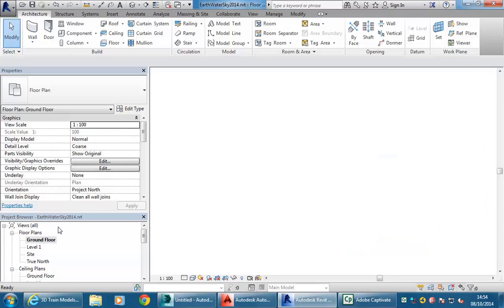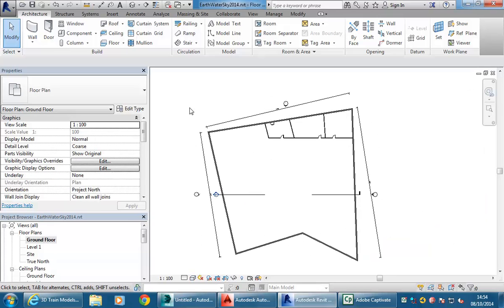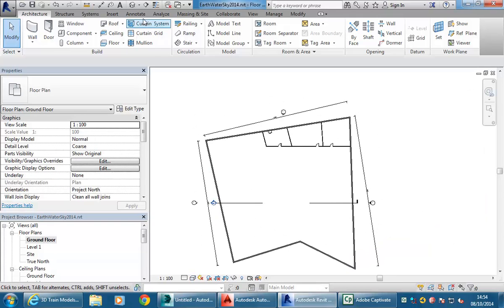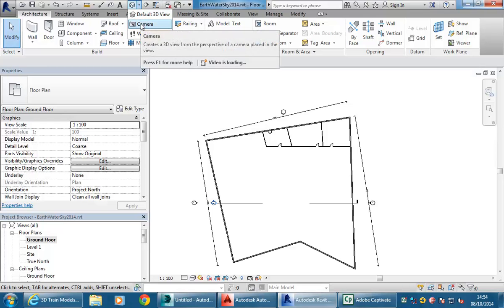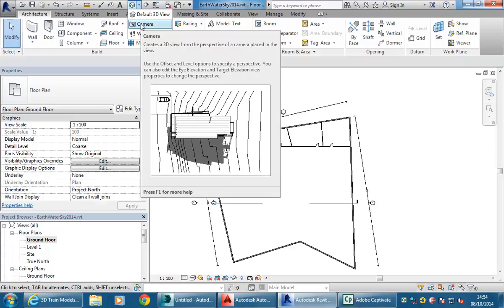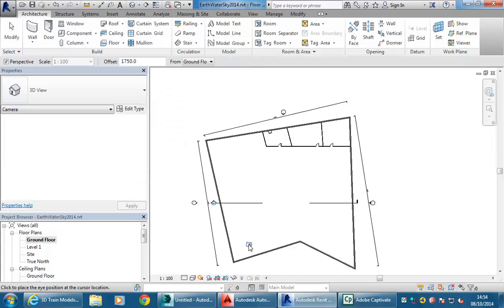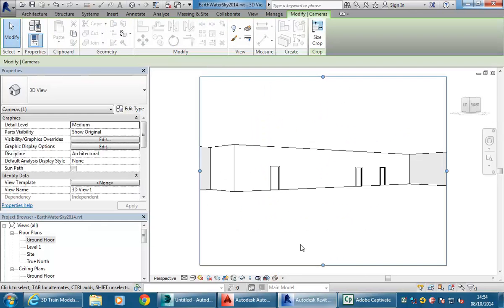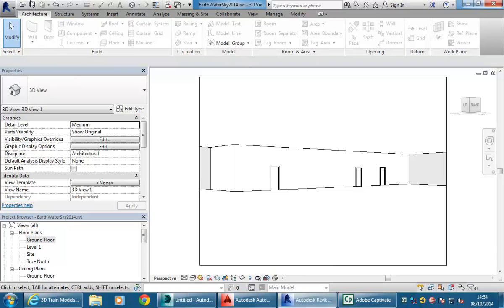Okay, so then to start looking at working with that in 3ds Max, the first thing you often want to have is a camera. So the camera view there, I'm going to just create a view through that interior, looking at those things I've created. Again, saving the file as I go.